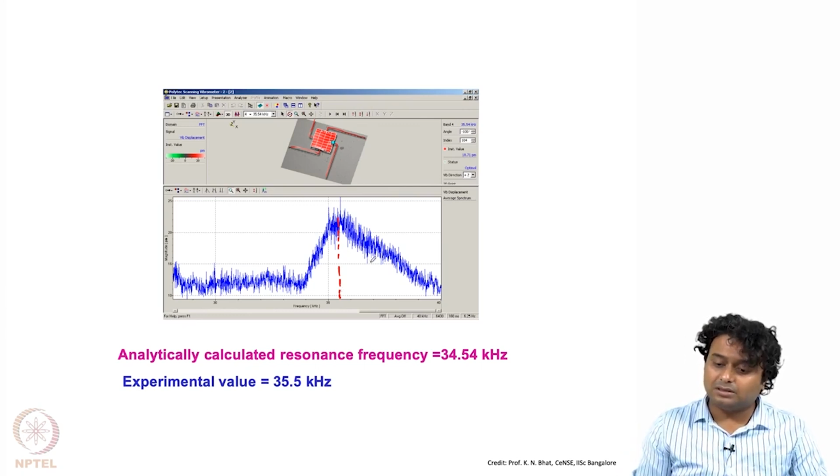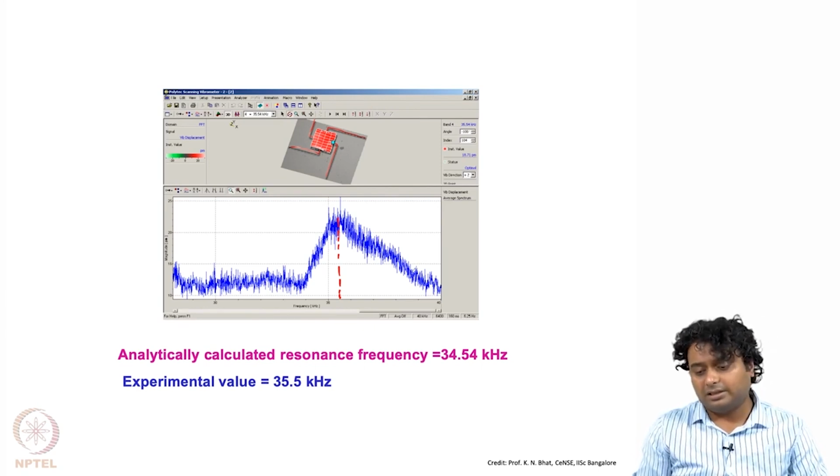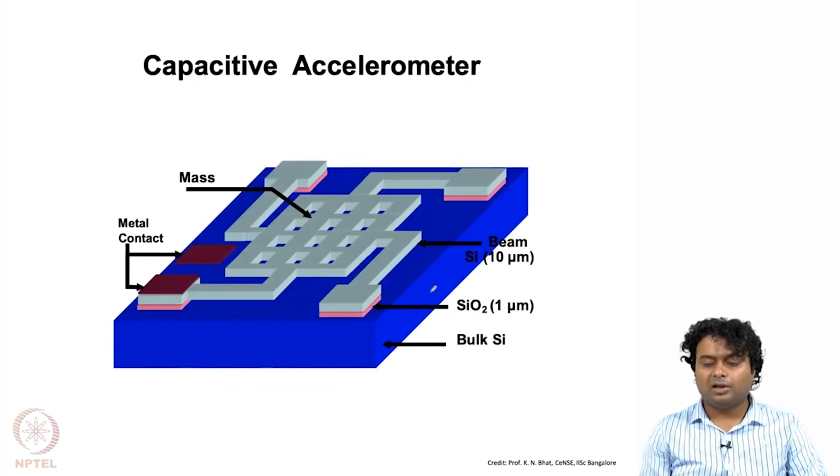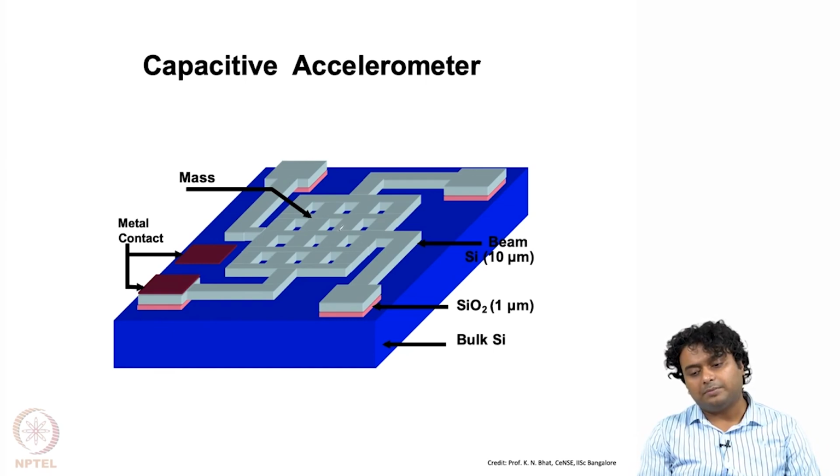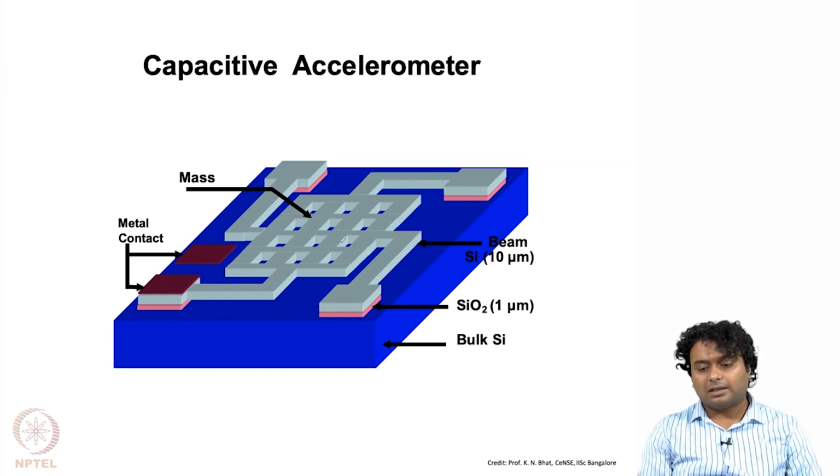And again, if we increase the forced vibration frequency more than the resonance frequency, then it decreases. While the structure is under some applied force, the frequency changes. Initially the membrane or proof mass is vibrated with some basic or forced frequency. As soon as some acceleration change occurs, we will see a change in the frequency response, and accordingly we can measure how much the acceleration is.